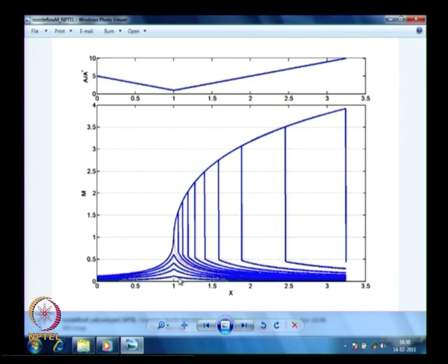If you look at very low Pb by P01 values, very close to 1, all the curves are here, it is going through fully subsonic solution and then it is going back to low subsonic. It increases closer to sonic, goes back down to low subsonic. There is a point where it becomes sonic and then goes through this path.